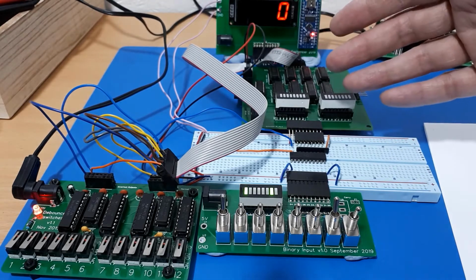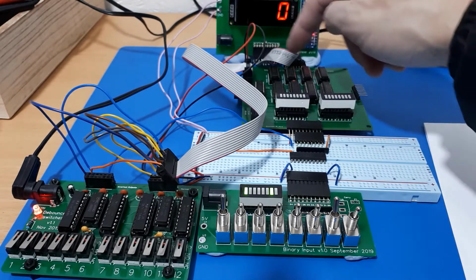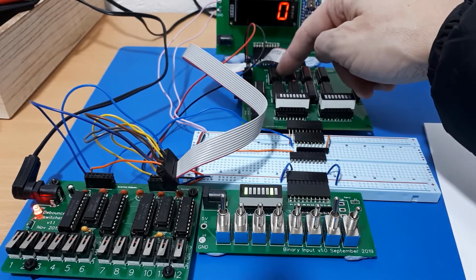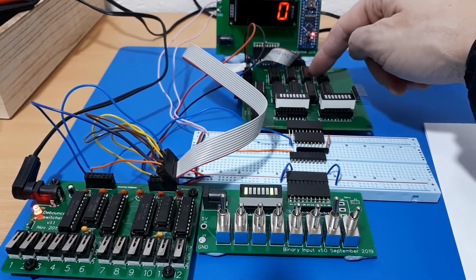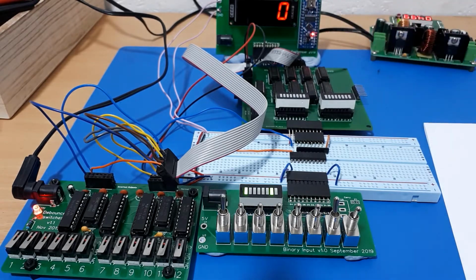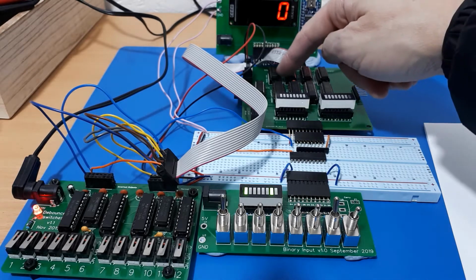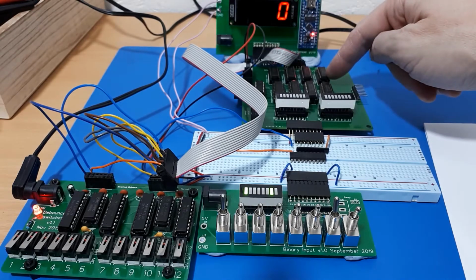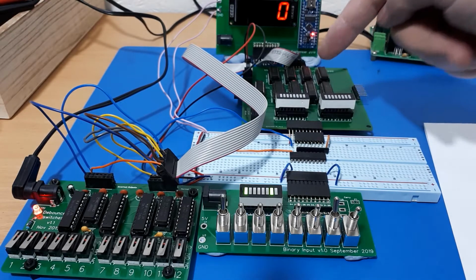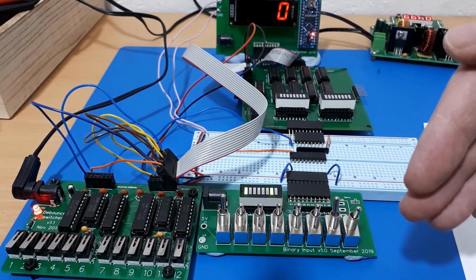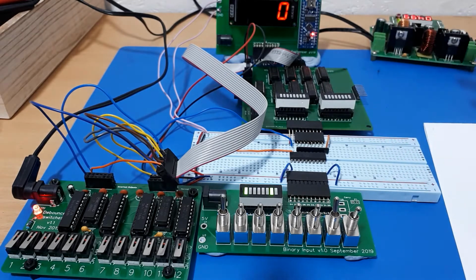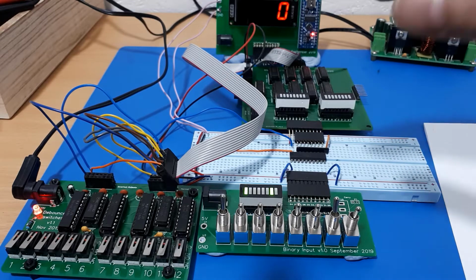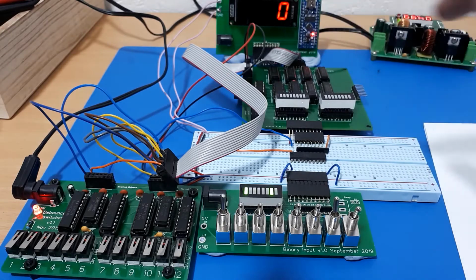We can increase the program counter a few times, and then we can get those 8 bits back out of the top 8 bits or the bottom 8 bits. We can get them back onto the data bus and read them. So when would you need to do that? Well, if you want to jump to a certain location in memory, you would set the value in the program counter. If you want to call a subroutine, you'd get the current value out of the program counter, jump to your subroutine, and when you want to return, you'd put the original value back into the program counter. So that's going to be storing it on the stack as a subroutine.